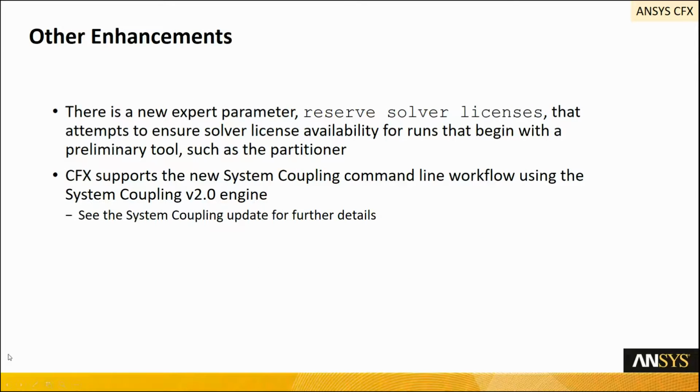Finally, a couple of minor changes. So the first is that there's a new expert parameter called reserve solver licenses that allows you to attempt to book licenses in advance, so that if, for example, you're doing partitioning, when it moves to the solver it will have the necessary licenses. And then secondly, as we mentioned earlier, CFX is now integrated into the new system coupling, so that you can run system coupling outside of Workbench using the new system coupling V2 engine.